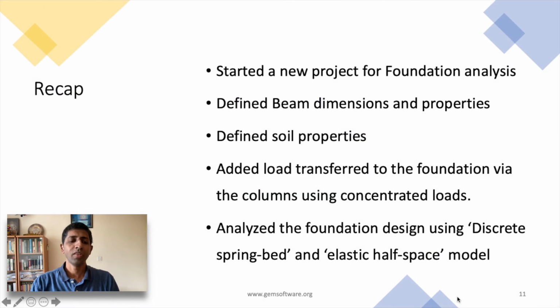To recap what we have done today, we started a new project for foundation analysis, defined beam dimensions and properties, defined soil properties, added load transfer to the foundation via the columns using concentrated loads, and analyzed the foundation design using discrete spring bed and elastic half space models.